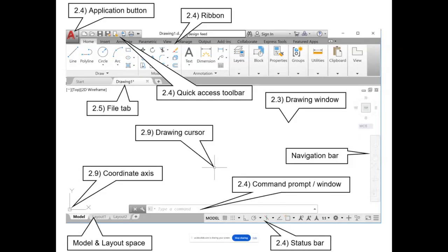And instead of using the escape button, we would do Control C to get out of the command so that it would clear it and say, hey, okay, I'm ready to start from scratch. Well, now you have to hit escape to do that. The main thing to remember is don't hit escape to finish out a command. You hit escape when you're in the middle of one and you don't want to be there and you want to restart. Because if you hit escape, let's say you were typing some text in and you hit escape instead of hitting enter twice, part of your text will probably disappear. You have to retype it.